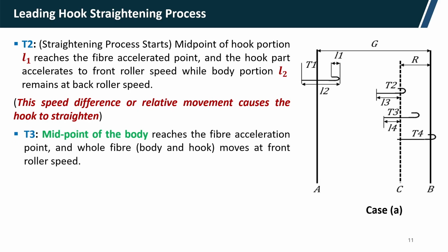Now, coming to T3: most of the straightening has taken place. At T3 the midpoint of the body reaches the fiber accelerating point, then the whole fiber, body and hook portion, will move at the front roller speed.